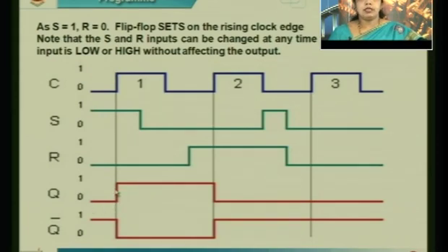So my output is now in set condition, that is nothing but logic 1. So Q remains logic 1 till where? Yes, it is till the next transition starts, even though you can just see here in between S has come to low, R has come to high, but my output remains the same as previous. This infers that whatever the inputs are at the edge, only those are reflected, and the same output is held until the next edge triggers.